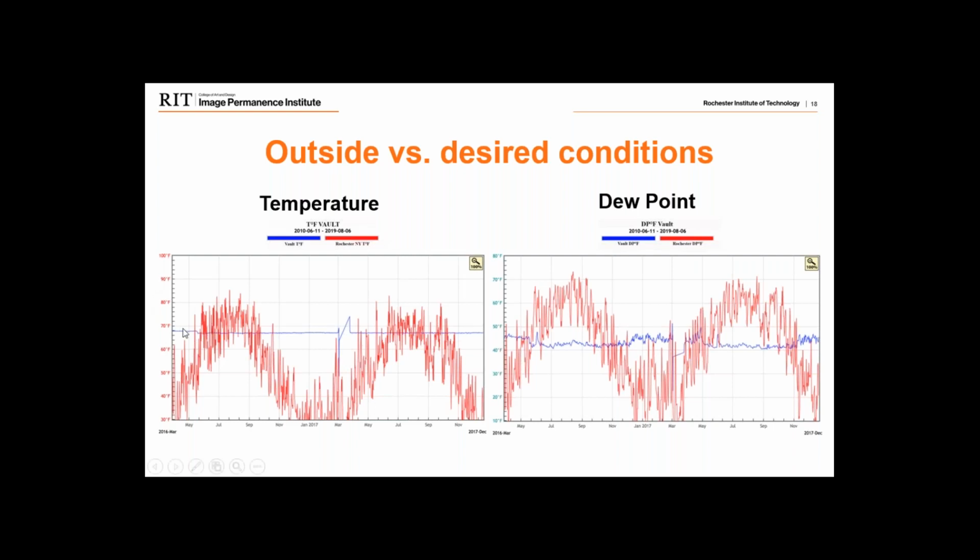So if we're trying to hold this 68-degree line, if we're using a lot of outside air, this is the amount of work that we would need to perform to achieve that. So as we have on the screen, anywhere above this 68-degree line, we have to cool that air that we bring in. If we're below that, we have to heat that air as it comes in.